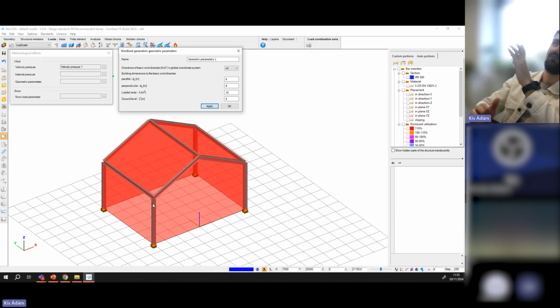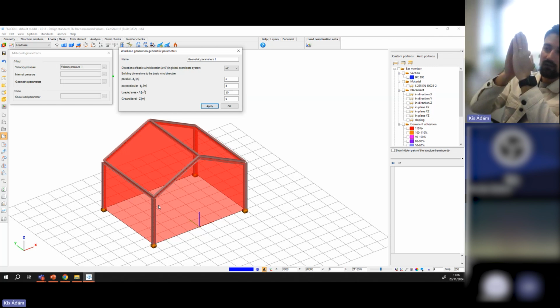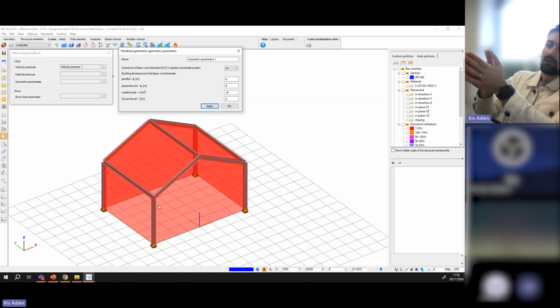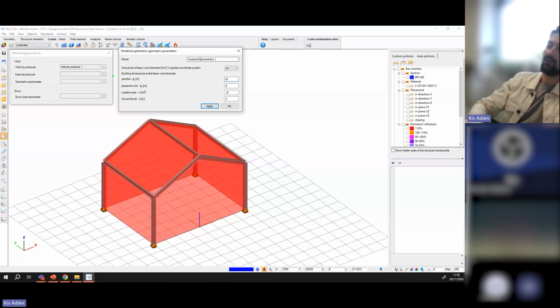If we have a structure with non-uniform heights and we have a tower, let's say, at the end of the structure, so we have different heights, and we are designing that exact tower, then we should write here the dimensions of the tower. If we are designing the whole structure, we should take into consideration the bounding dimensions of the structure. But again, these are only used to recommend a certain meshing value, which I will show you immediately.